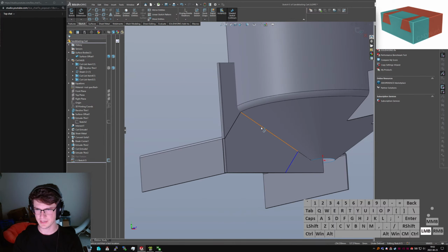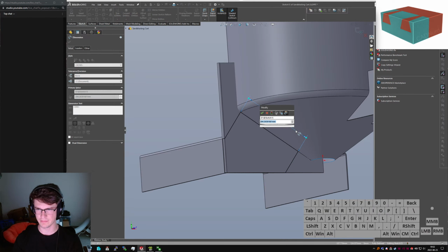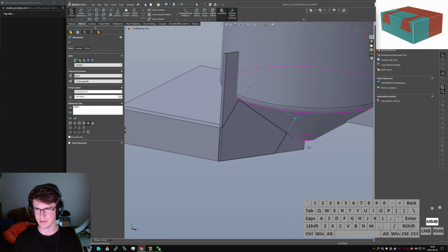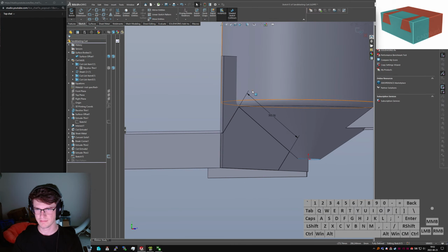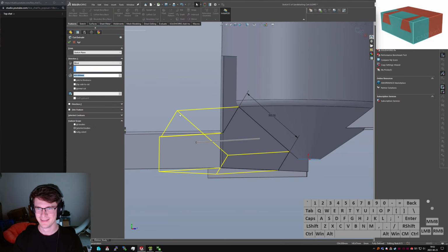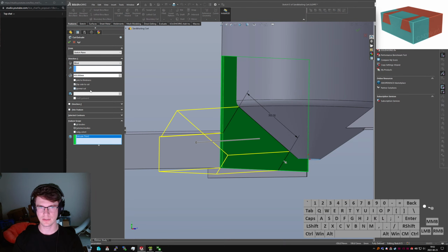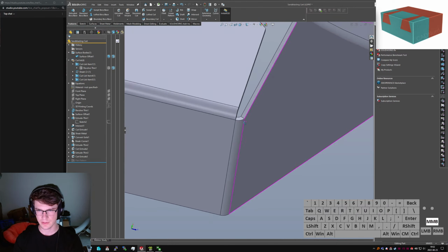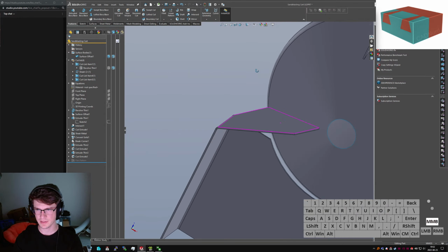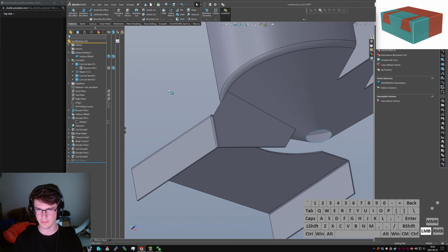We'll say that this has some length of 300, actually be really nice. That almost looks like I did that on purpose. I promise I didn't. So we'll do flip-sided cut. Don't auto-select bodies, just do this one. And it should give us something that's not too unreasonable for a body there.